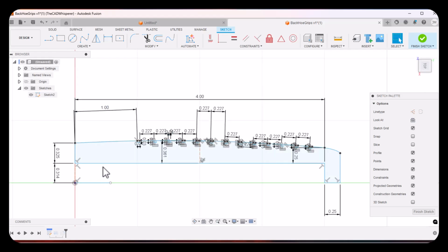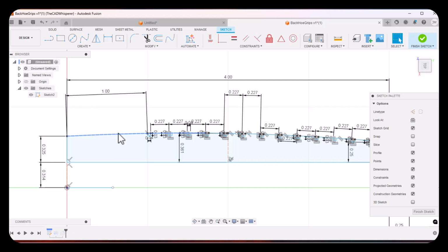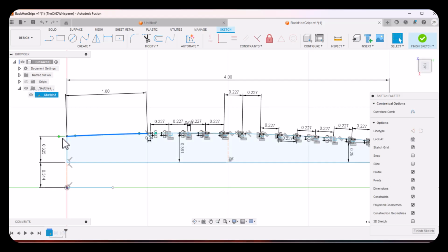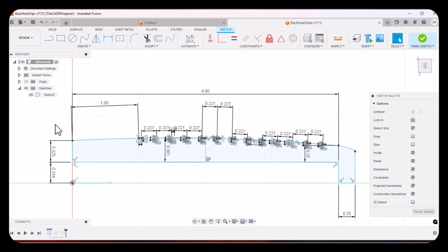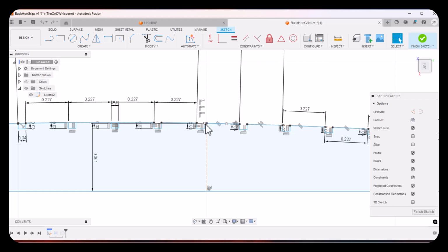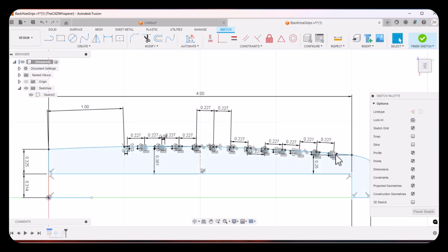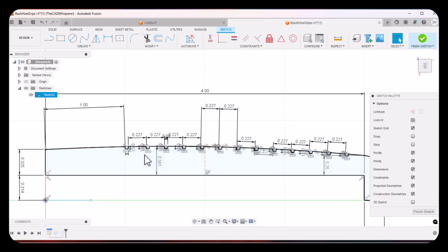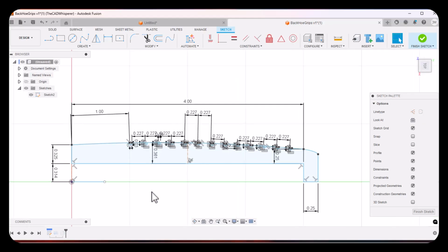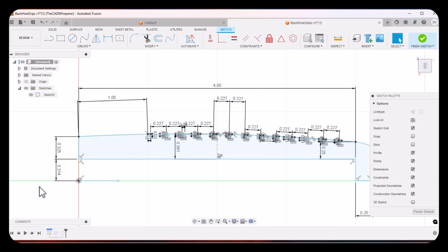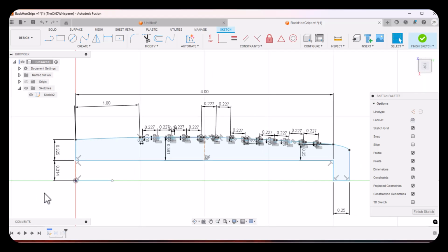As I continue further with this, I observe that these curves are splines. I can tell that by the handles on the end of them. Splines are a more complicated geometry. I did a single 3-point arc from here over to here up to this given point here, and that arc closely matched that spline. If the greatest distance was somewhere over in here, the discrepancy was 1/1000th of an inch. That would be even difficult to measure, let alone hold that tolerance in manufacturing.